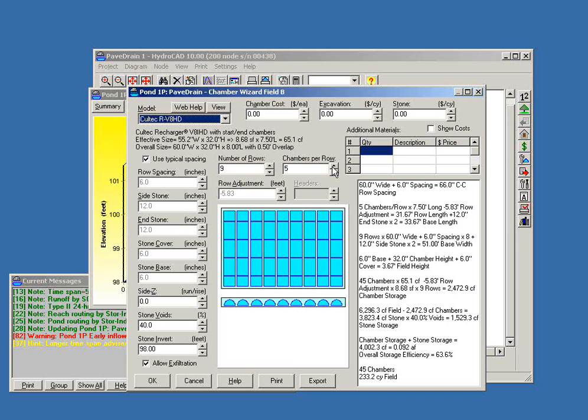The smallest stone that we incorporate under Pavedrain is a 3/4 inch clean. The reason we can get away with this is because the footprint of the block is so much bigger than a traditional little paver. This block has a footprint of about 1 square foot. That means we can get by with bigger rock, which makes things easier on the job site.